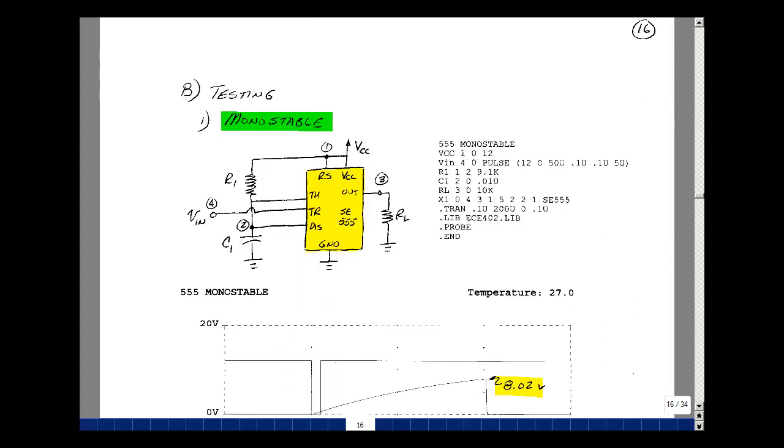No matter what the model is you're going to use for any IC, one way to test it is to come up with a set of test circuits, that is, to build circuits that we are familiar with and kind of know what the answers are supposed to be. So whether we're using a full transistor schematic to simulate this chip, or we have a model, like I did with the 555D model in the PSpice library, I can see whether the model works or not.